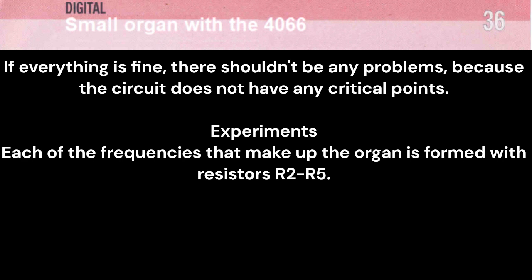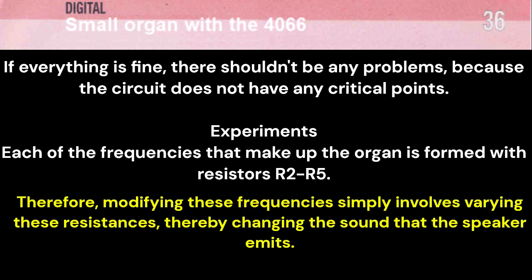Experiments. Each of the frequencies that make up the organ is formed with resistors R2 to R5. Therefore, modifying these frequencies simply involves varying these resistances, thereby changing the sound that the speaker emits.